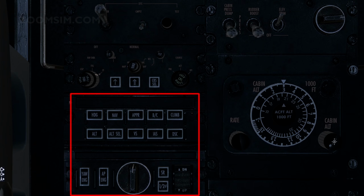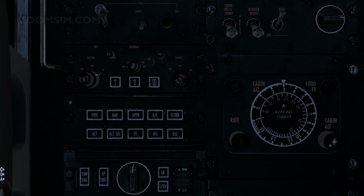Autopilot check. Yaw damping and autopilot should not be engaged during takeoff. Electric trim check. All surfaces are manually trimmed, however optional elevator electric trim is available. The elevator trim switch must be placed in the on position to arm the system. The elevator trim tabs are then actuated by an electric motor in the fuselage aft section.